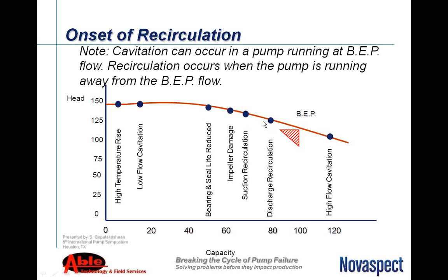If you've ever heard the cavitation noise, you can also possibly hear recirculation occurring. Or if you see wear on the side of the volute, you'll know if it's recirculation or cavitation once you pull the pump apart.